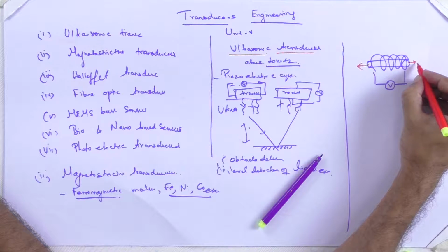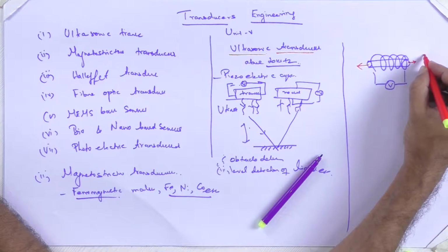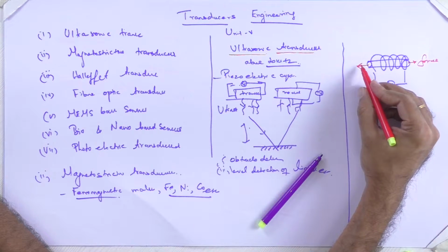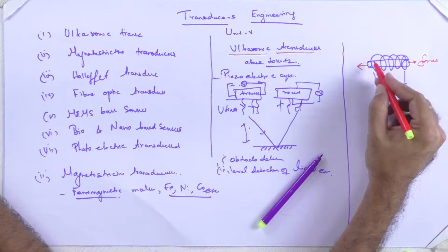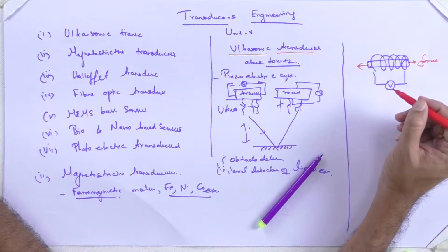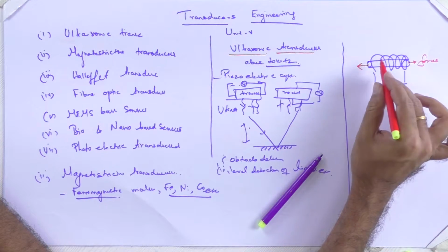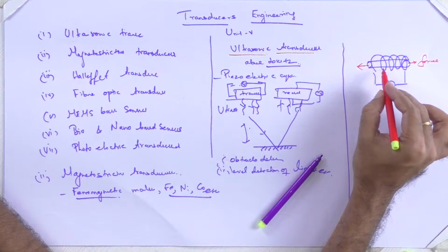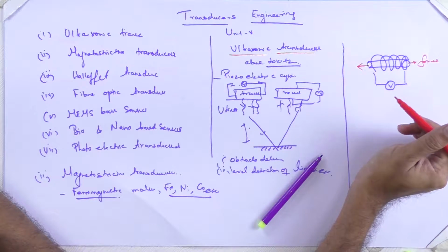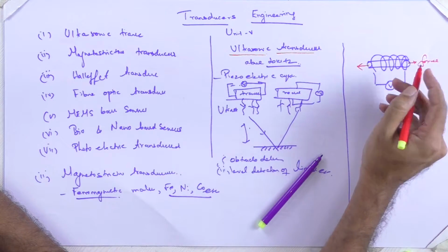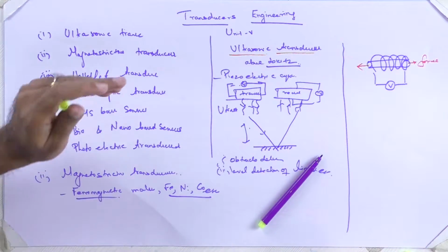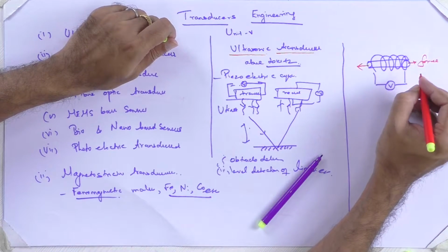This red line that I am indicating is the force that is produced. So there is a conductive coil and the magnetostrictive ferromagnetic material over which the coil is wound, and when we give in or change the magnetic flux, a magnetostrictive force is produced, or a change of mechanical stress is induced in the material. This force or stress which is induced is represented as displacement.